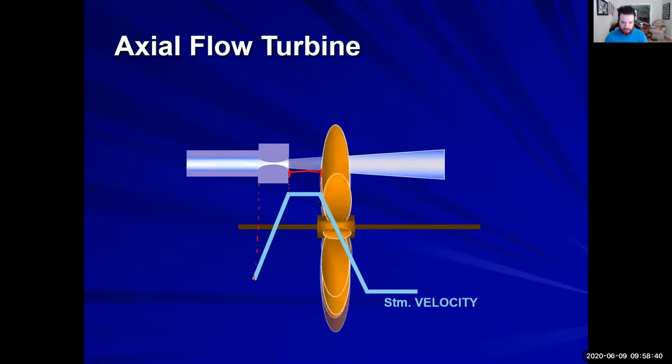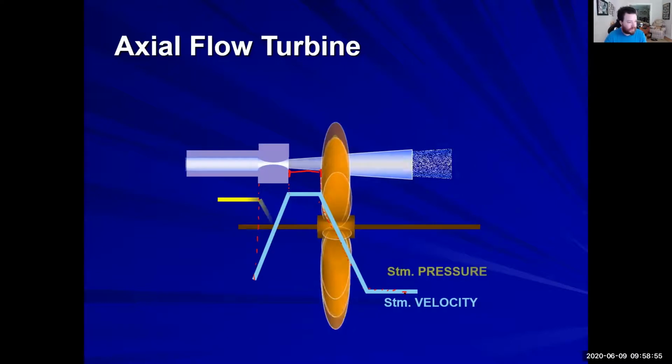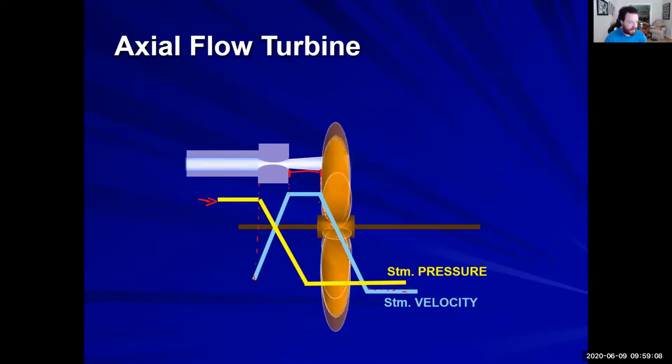And what we're doing is imparting energy onto the turbine until we leave the turbine blade and we peter out. So we can't just create this energy from nothing. We're using basically our steam pressure, so it has the reverse effect. It has a high pressure leading in to the nozzle, and as soon as it hits that nozzle and we start to increase our velocity, we are going to be decreasing our pressure. So where we're giving up pressure, we're increasing our velocity.